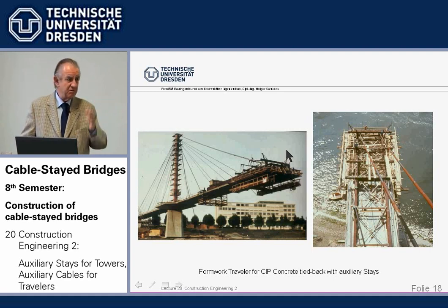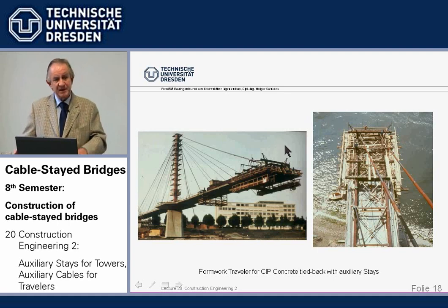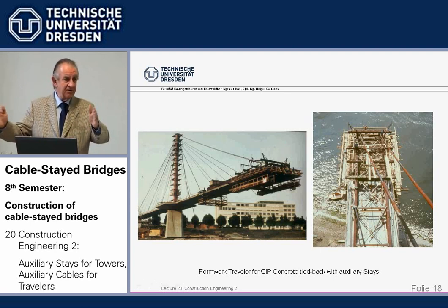That may be something like 10 meters, roughly speaking. And then depending on the depths, if we have only 1 meter depth of a beam, and cantilever that 10 meters, that's 1 in 10 for a cantilever. And there we realize already, maybe too much for the beam.